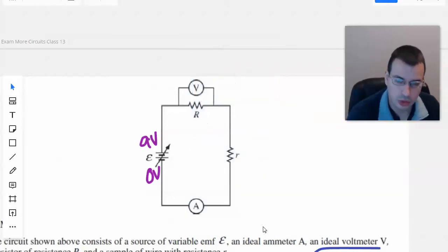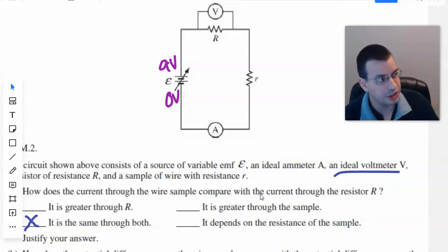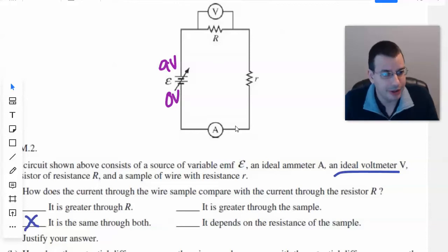And so even though we know the current through both of them will be the same, regardless of the resistor sizes, because one current comes in, one current comes out. You could say that's Kirchhoff's current law, or you could also use the hydraulic analogy and say, look, this is just water in a pipe. If you start with so much water, you're going to end with so much water. If you don't, then there's some terrible leak in the pipe, or you have compressible water, which, though possible, is assumed not to be possible.